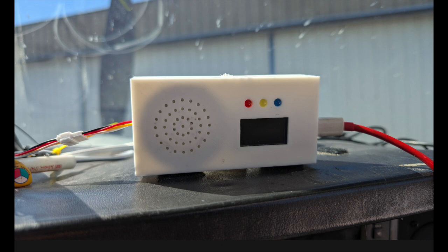The power supply comes in on the right side, the USB, and on the left side you can see the 4 wires going to a connector, which then is routed down temporarily to the outside of the aircraft through one of the air vents, and the sensor is mounted under the wing. So I calibrated out the wing height, which was about half a meter or so, and took that out of the equation as far as the height of the aircraft above the ground. So that gives you a 0 level.